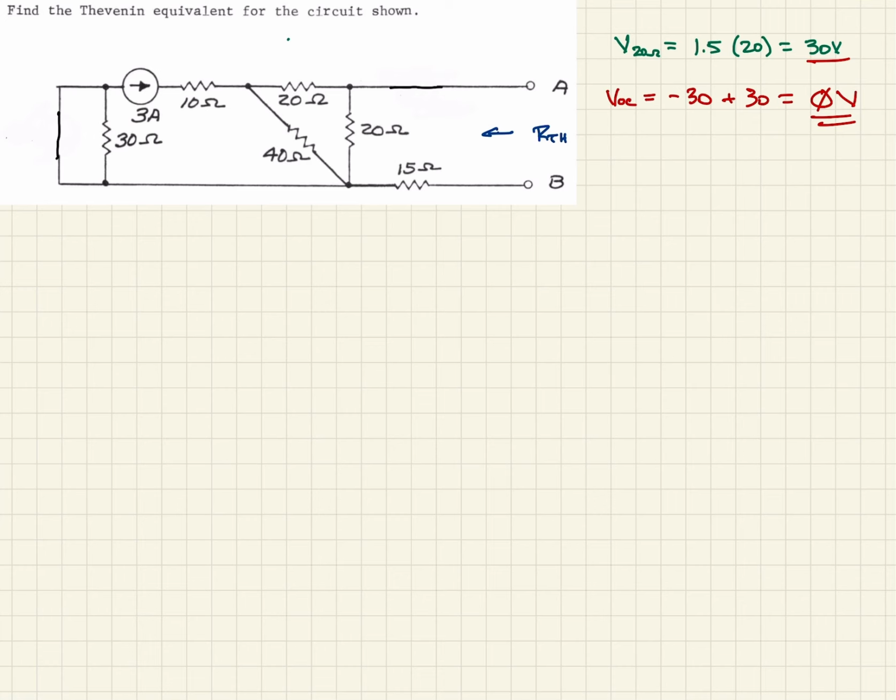And we open circuit current sources. So that being the case, it's like this guy is gone totally. But in this case, we don't replace it with a short. We just leave the terminals open there. So looking at this, this no longer has any role in our input resistance, right?